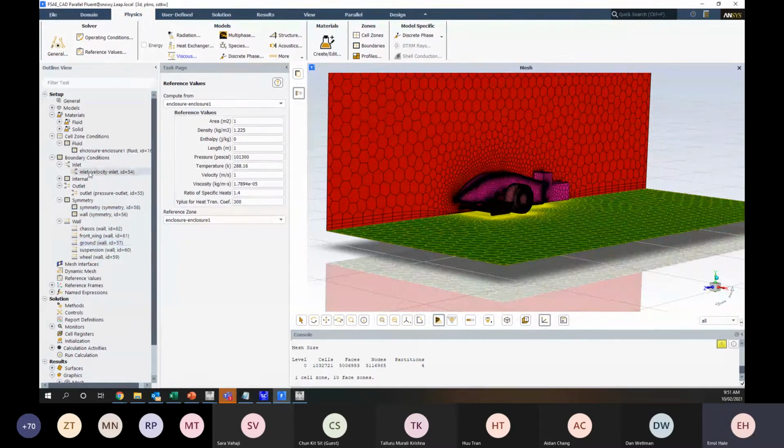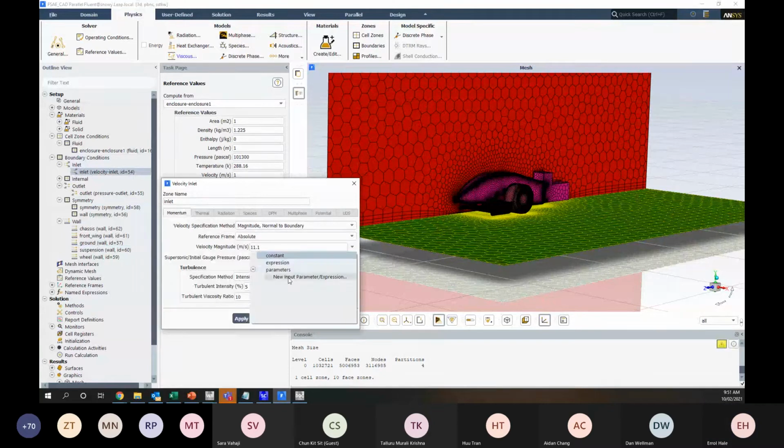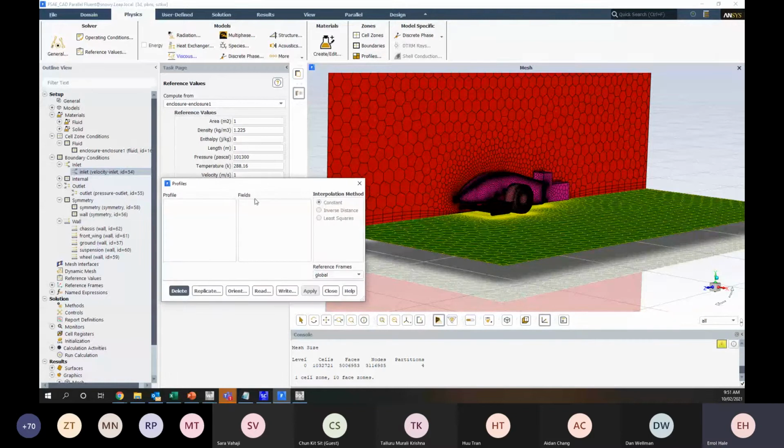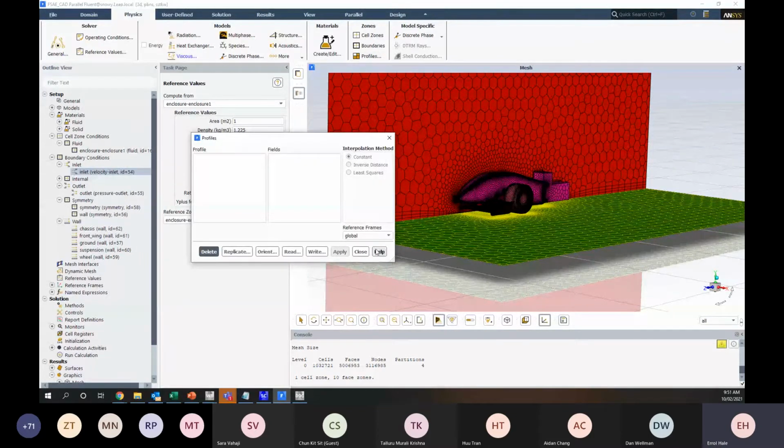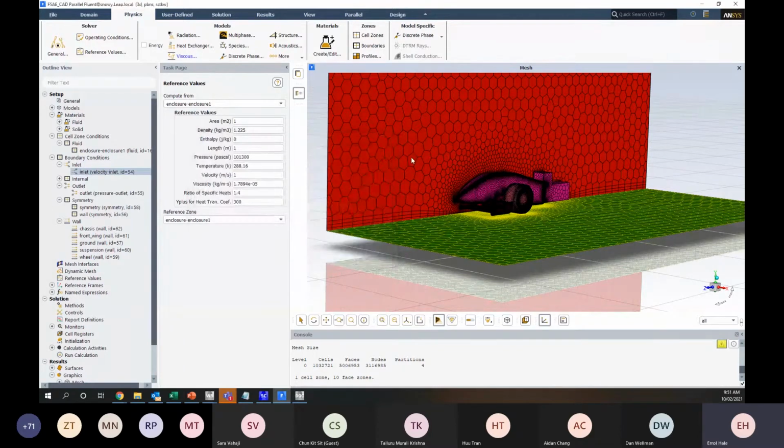And you can do that by entering a profile. So in here, we can enter a profile. We could essentially take the profile at the outlet. If we wanted to use the outlet profile of one simulation as the inlet profile of another, we can take a profile from the outlet and specify it as a profile for the inlet of the other. That can save us on computational expense by not having to have the inlet so far from the region of interest, because that space might be necessary to allow the flow field to fully develop before hitting the region of interest.